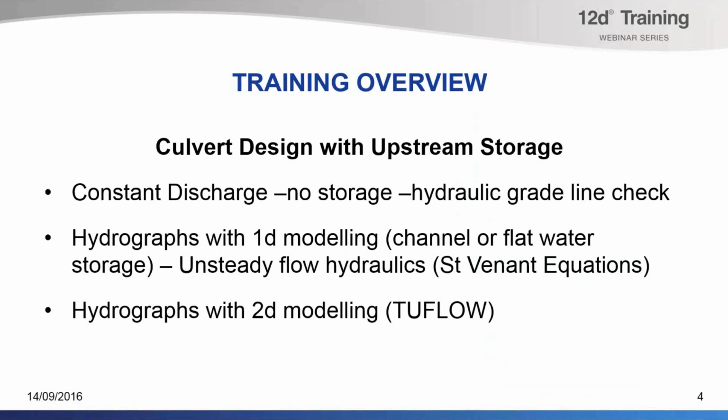This will involve using hydrographs, first of all with 1D modeling, and upstream of the culvert we'll either have channels or we'll have flat water basin storage. In order to calculate the flows through the culverts in these cases, we're going to use unsteady flow hydraulics, which is solving the St. Venant flow equations.